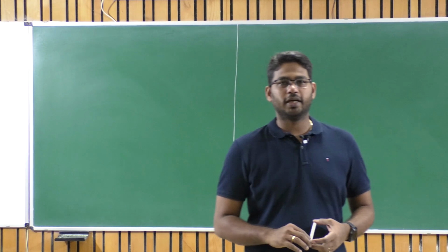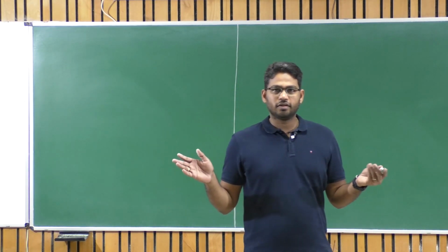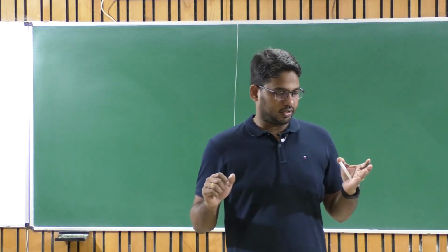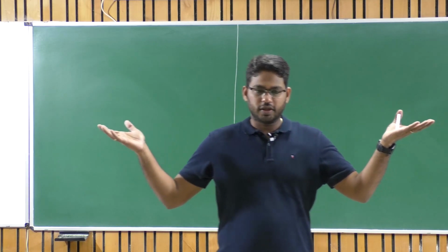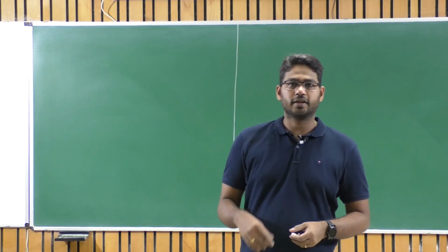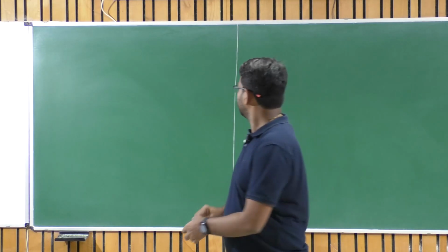Dear friends, welcome back. In our previous lecture, we discussed a wing and tail combination and the stability of that wing and tail combination. We derived the neutral point for the wing and tail combination, which turned out to be the weighted average of the lifting characteristics of the wing and the tail, right? So we started with